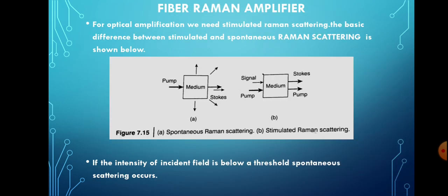Next, we can go to the details of the fiber Raman amplifier. Up to this session, we have discussed the Raman scattering phenomena, the spontaneous Raman scattering, and how the pump wave is transferred to Stokes or anti-Stokes waves. Now we will go to the fiber Raman amplifier, and for optical amplification in a fiber Raman amplifier, there should be stimulated Raman scattering.